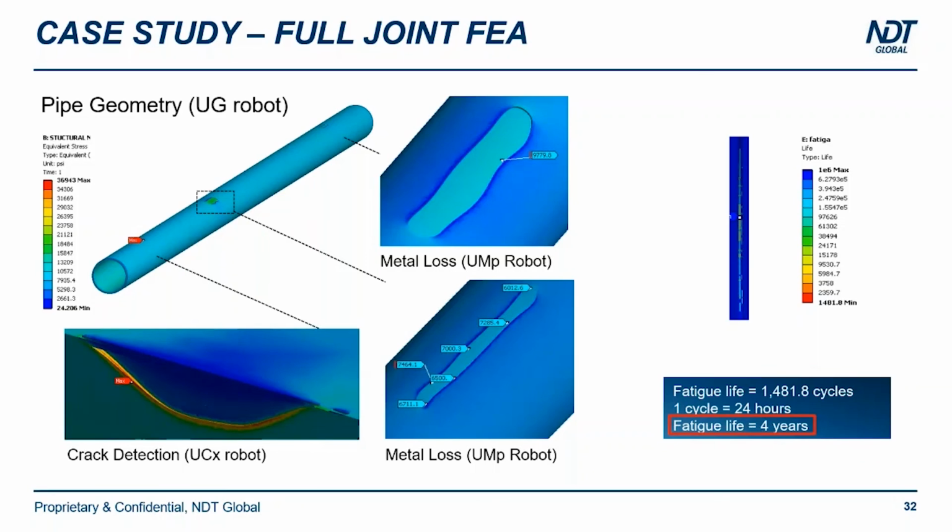Additionally, with the FEA, it's possible to assess the fatigue life of the pipeline subject to analysis. In this simulation software, we consider one operative pressure variation and one time value that defines the load cycles. It's possible to use the operative records, of course, but in this case, the customer defined the operative cycles between 700 psi as minimum value and 1,400 psi as maximum value, with one time between one value and the other of 24 hours, 1 day.